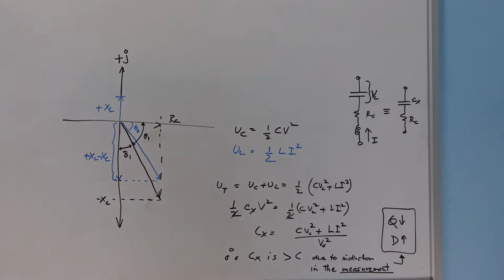So we just derived the impedance of a capacitor in terms of the resistance, ESR, and capacitance, and the frequency and so on. But let's quickly look at one more thing, and that is the phasor diagram of the impedance itself and how it's affected by the reactance and the resistance. So on the real axis, the x-axis, we have the resistance here, and on the imaginary axis, the j-axis, we have the reactance.